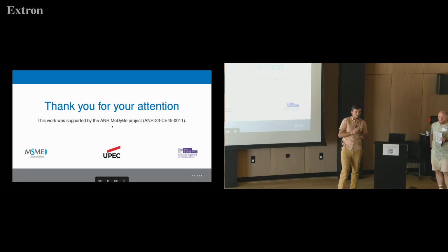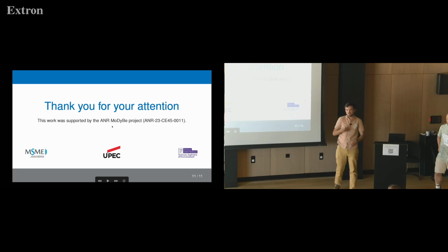But my question was in a similar way to before. Have you considered where you don't have a body-fitted mesh, let's say you have a fixed mesh from the beginning, just like a cube of the whole domain, and then your bodies are just fields that are convected? An Eulerian approach, so that you don't have to move the mesh nodes, so you don't get distorted elements or cells. Have you considered that? No.